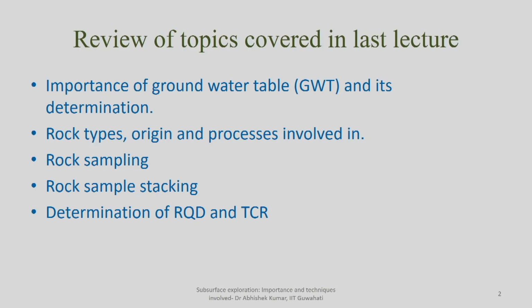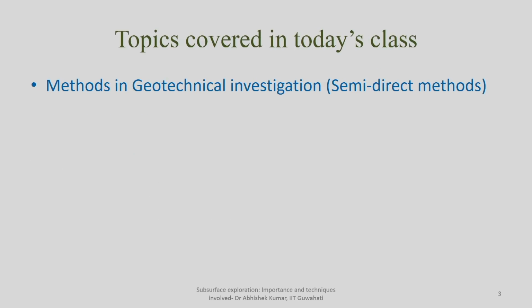And then we discussed the different bits you can use, whether you are drilling in a soft rock medium or a very hard rock medium. So you can go anywhere from a carbide drill bit to a diamond bit also. So this was the topic we had covered last time about rock sampling.